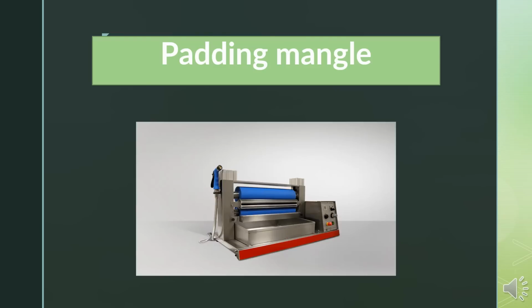What are the following steps? The first one to follow is a hot chamber that has hot air at a particular temperature blowing through. This heating chamber helps in making the dye react with the fiber chemically, or penetrate inside physically, as the case may be. A set of press rolls ensure that the excess dyes and accessories picked up from the padding mangle are removed from the cloth even before it enters this heating chamber.